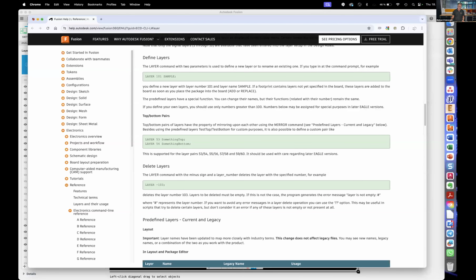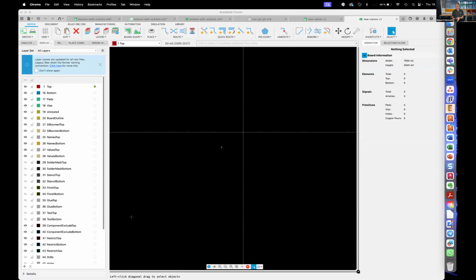So what I wanted to show you is something about working offline in Fusion Electronics. I've seen a question in the chat about offline. In electronics, if you are not online, all the cloud-related things, 3D models and so on, it's not possible to use them. Of course, you can work offline, you can save your files, but when it comes, for example, to defining a library, until now it was not possible to work and create a library. Now you can do it.